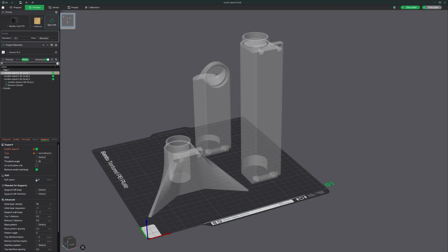Basically, what it's going to do is your print is going to be printed on top of another piece, in which you can indicate how many layers that's going to be set here. This is also one reason why it doesn't get used as much anymore, because we have heated chambers and such. If you were trying to print ABS on a bed slinger that didn't have an enclosure, you would probably be trying to print something on a raft.